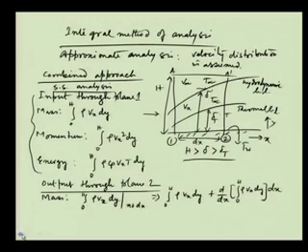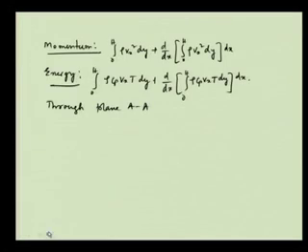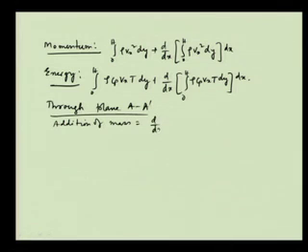If I see that this A A dashed, okay. Now, the addition of mass, that will be equal to the change of mass, which is nothing but d/dx of the integral from 0 to h of rho v_x dy. This is the change of mass with dx as we move forward, so into dx. How is this mass coming into the boundary layer? It is coming from the other sides. So d/dx of this is the change of mass, and into dx is the total additional mass that has entered.